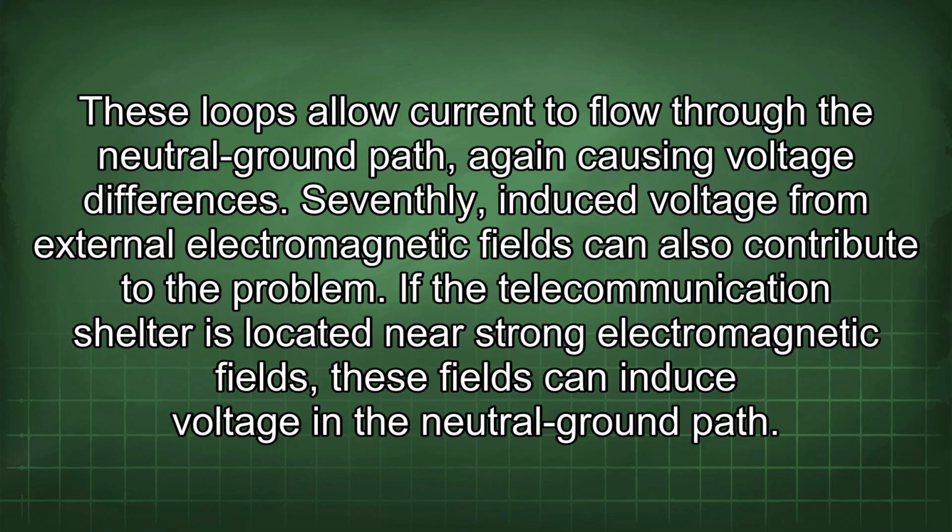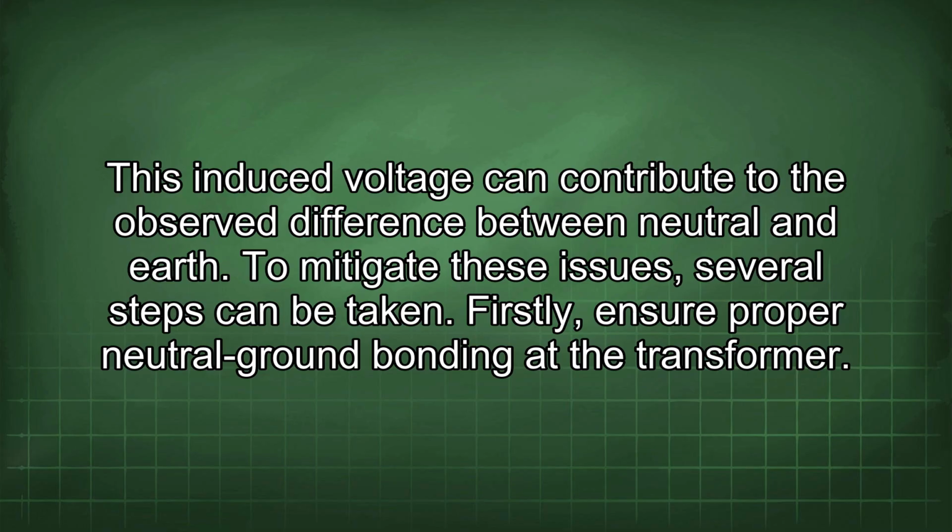Seventhly, induced voltage from external electromagnetic fields can also contribute to the problem. If the telecommunication shelter is located near strong electromagnetic fields, these fields can induce voltage in the neutral ground path. This induced voltage can contribute to the observed difference between neutral and earth.